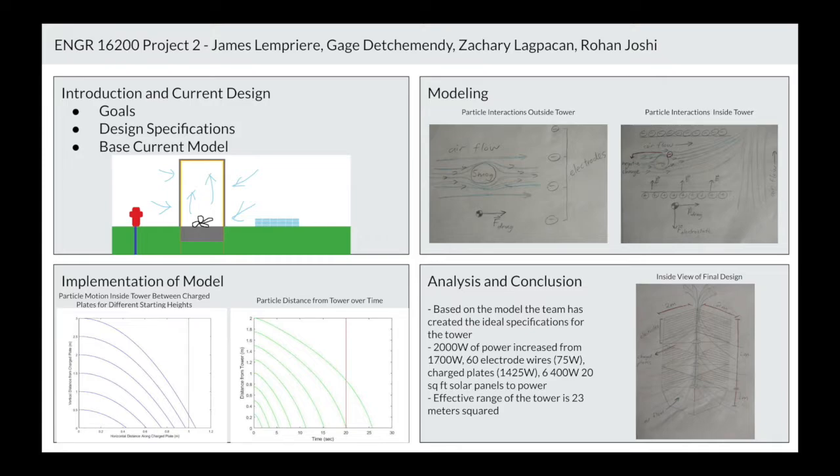Along with the assumptions around the forces involved, the model must also make some assumptions with respect to energy usage. The energy used by the fan would follow a proportion where, for example, at half the volumetric flow rating for a given fan model, half of the energy would be used. The energy used by the charged plates would follow the power required to flow 1 ampere through the system for a given potential difference between the plates. And finally, the energy used by the electrodes would follow the energy required to isolate the point charges of the electrodes given the distance between the electrodes.